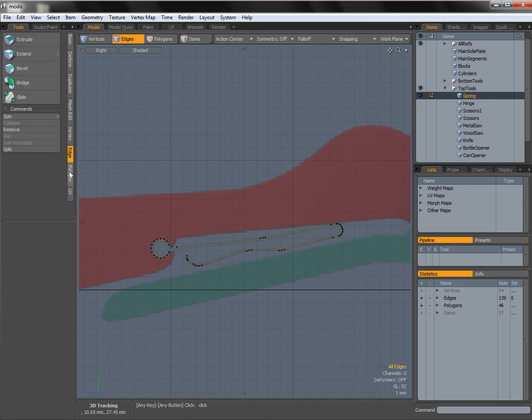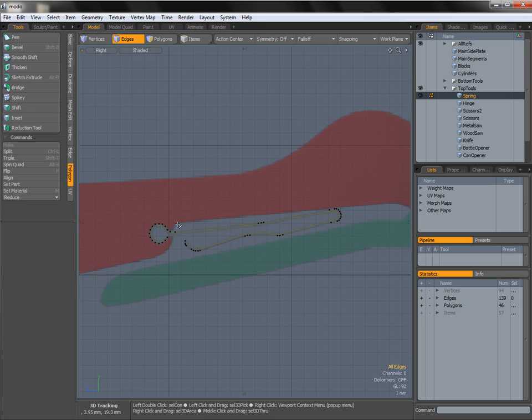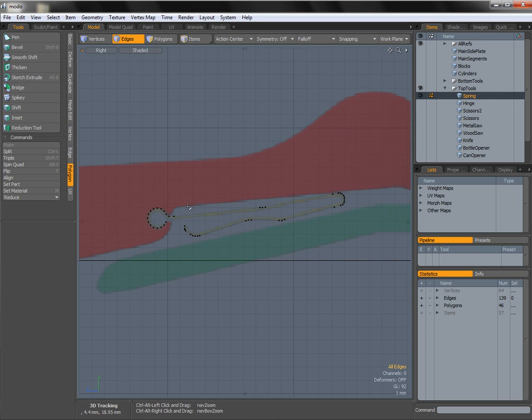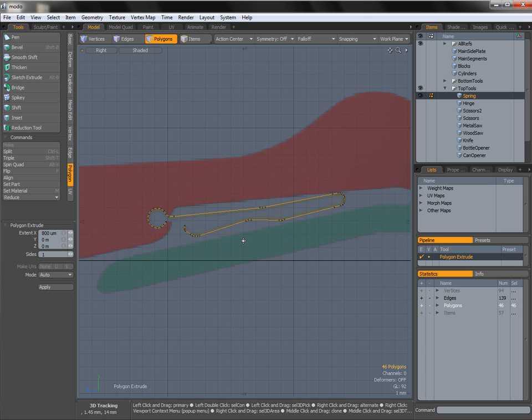And that's found over here in the polygon menu in this top section, so it's the 4th one down. Now the thicken tool is a bit like the extrude tool and a bit like the bevel tool. It's a combination of the both. Now if I was to grab all of the polygons that we have, hit X for the extrude tool and right click, if I was to move them, we're not taking into account the normals of these polygons. And the normals is essentially the way they're facing.